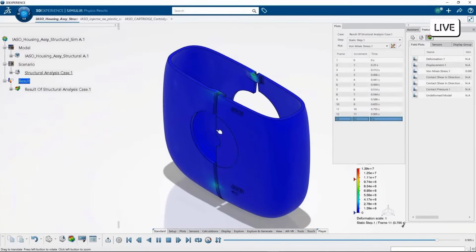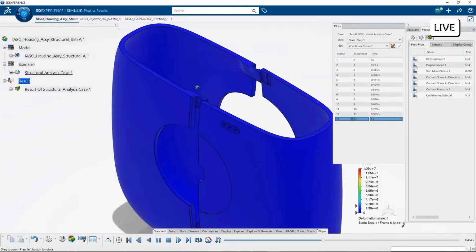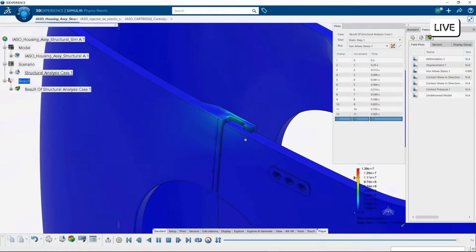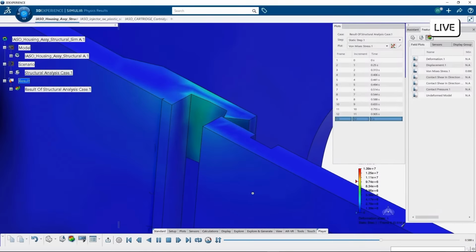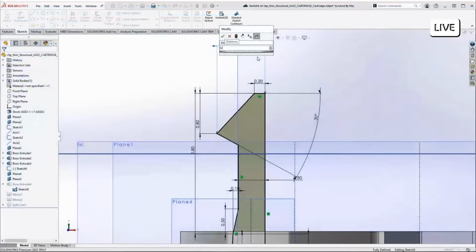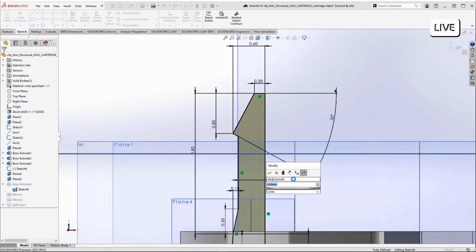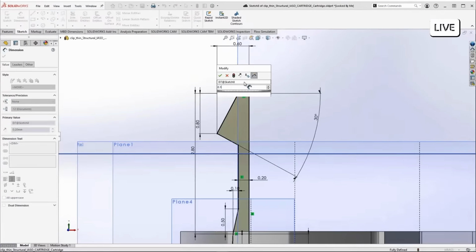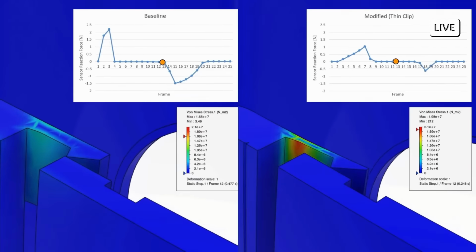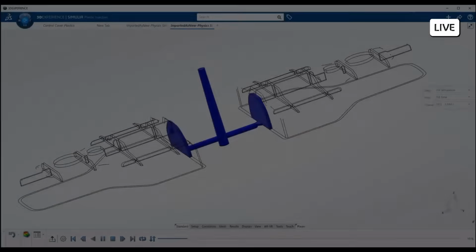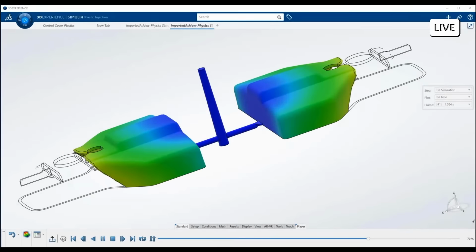And because of the platform environment, you can take those results into the structural analysis package and do a snap fit analysis like the ones that you're seeing here, just to ensure that you have the fiber orientation in the right direction, where strength is desired, and whether the snap fit is going to work as expected, or is it going to break in real life?